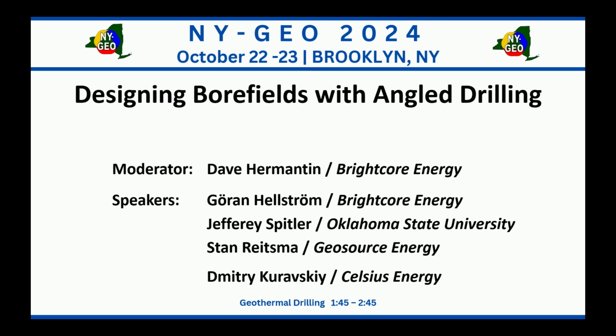I talked with one of the more experienced drillers in Stockholm, where we were drilling crystalline rock. And he said he was very comfortable with drilling up to a 20 degree angle. After that, there was some concern about working conditions for the driller, because it was kind of heavy to direct the rods into the connecting of the rods at an angle.